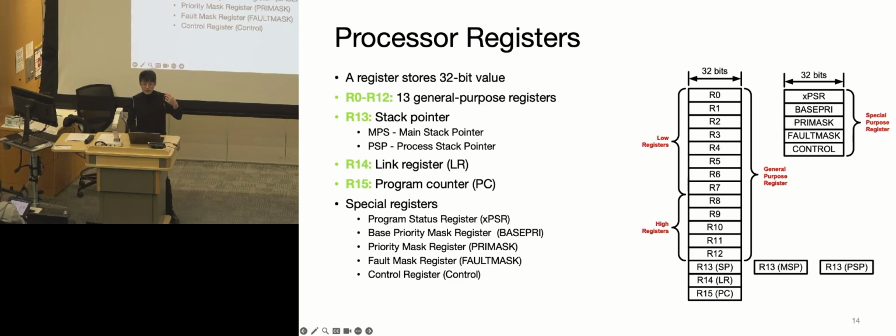That's where you push the data in the registers, so that it can be saved once the program comes back to the previous location. We also have R14 as the link register. That holds the address you will be returning to if you are inside some subroutine call. And the program counter keeps track of your current memory location, in terms of the instruction you're running.